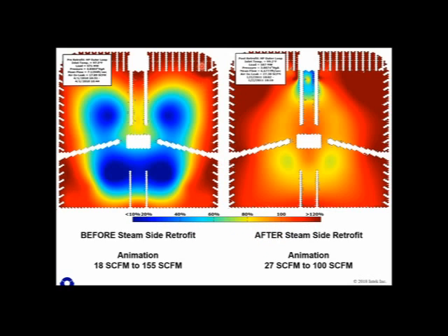So you can see here, often I get questions, by the way, please ask questions. Often I get questions about this outer edge being above 100%. How can that be possible? Well, we talked about that yesterday. HEI is a conservative estimate of single tube heat transfer values. The ASME method is a much better representation, and it produces heat transfer values about 20% higher than HEI. Out here you have very high velocities, no condensate loading, and so you get much higher heat transfer coefficient values on the periphery of just about any bundle. And they approach about 120%, very near the ASME values.